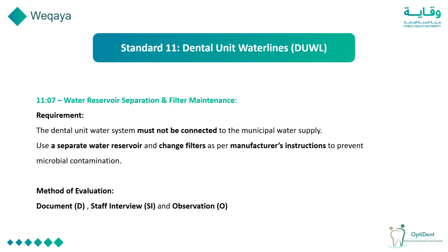The dental unit water system must not be connected to the municipal water supply. Use a separate water reservoir and change filters as per the manufacturer's instructions to prevent microbial contamination. Also, the filters are very important. You have to make a schedule for the filters to be changed, and it's based on the manufacturer instruction and recommended time for changing them.